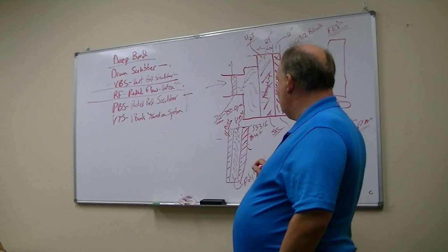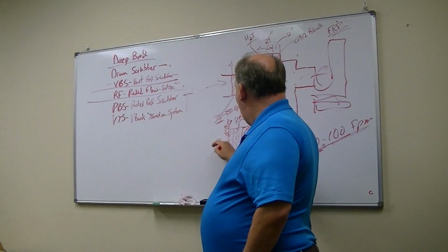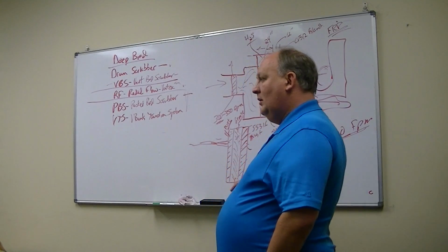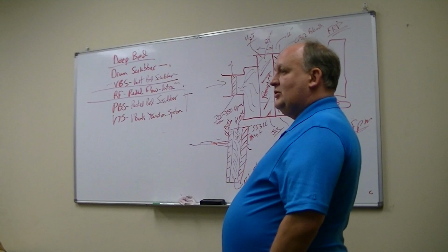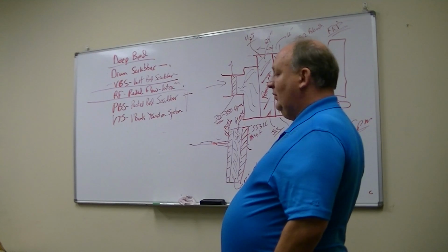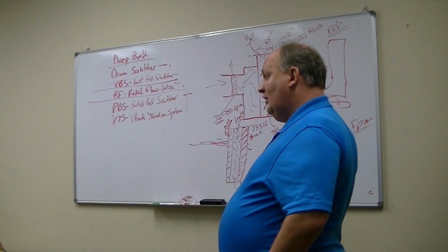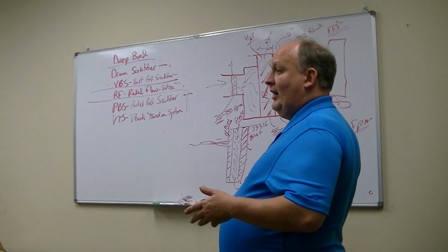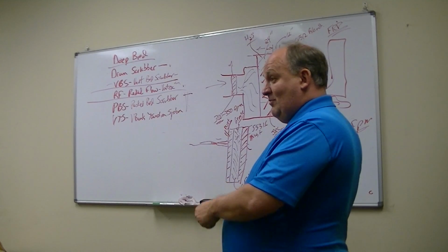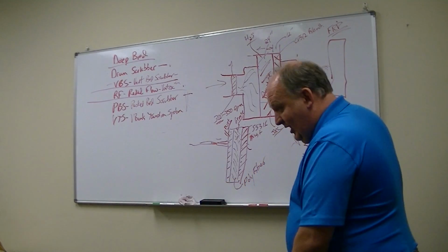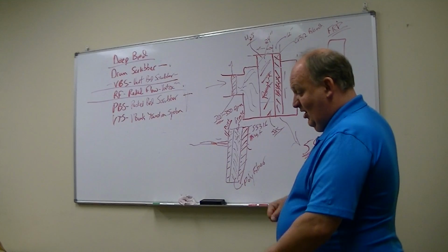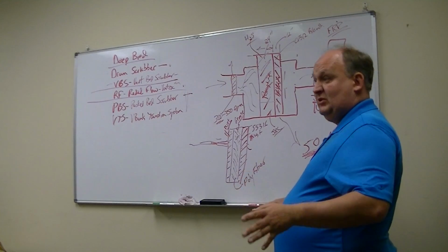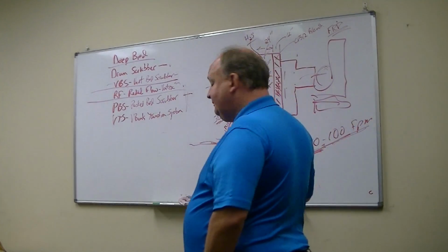But even at that, you're not really going to drive that dirt out because there's dirt and grease in there. Afterwards, you've got to go in with a pressure washer and really hit this thing hard and wash that mist and grease filter out. So hopefully it'd be nice if you could do it with hot water. One of the best ways that I've done with a customer, I took one to a car wash, a manual car wash, and just went in there, and when you hit that thing, you'll see all the real nasty dirt coming out, and then you just do it until the water turns clear from it.